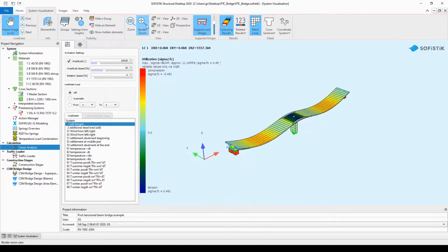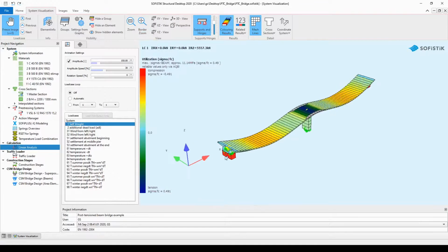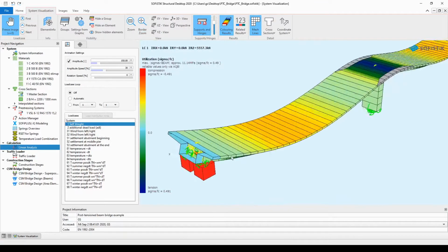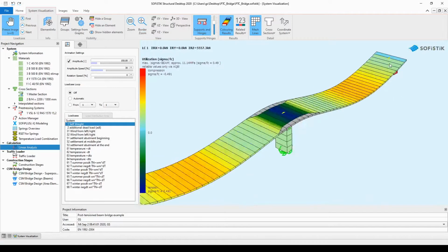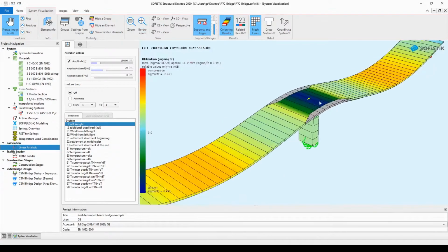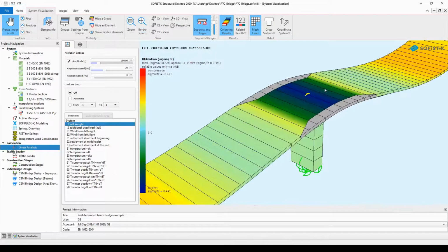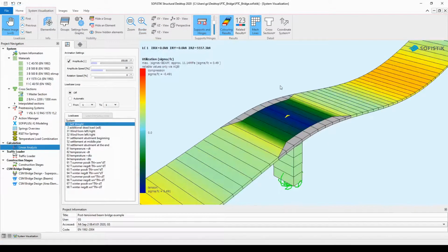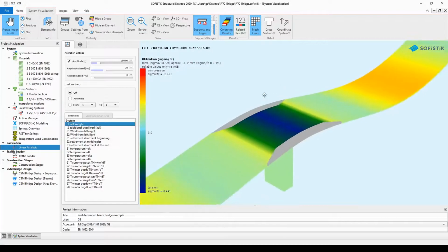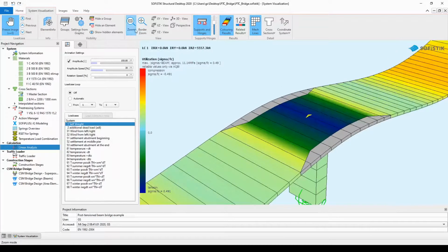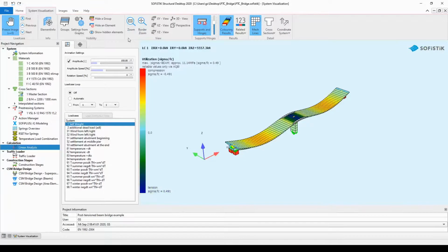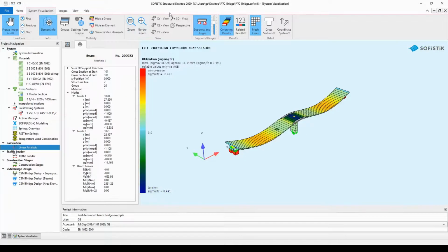the border zoom button. However, a very good zooming and zoom extent option can be achieved by scrolling the middle mouse button, and you can also zoom in the part of the structure that you would really like to represent. Combining this with the dragging when you push your middle mouse button makes the zoom and the zoom border buttons very rarely used. With the help of the next few buttons, you can set the view of your structure.